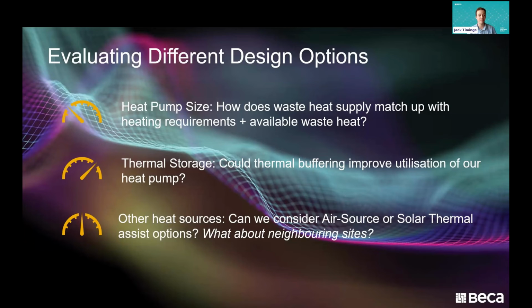Thermal storage, I think, is a massive enabler for heat pumps to do more with less capacity, because it helps smooth out those operations if the hot and the cold side are out of alignment or one's less continuous than the other. So we ended up installing a low side thermal storage unit to allow us to bank up that low temperature energy over the day, so that we can use it at night when the hot water system was really busy.